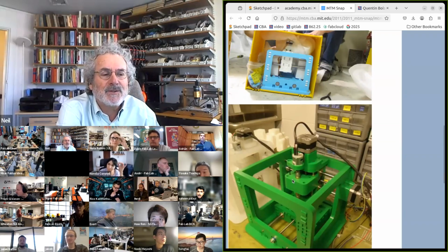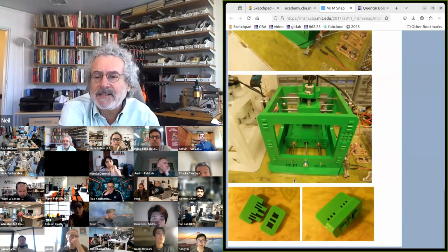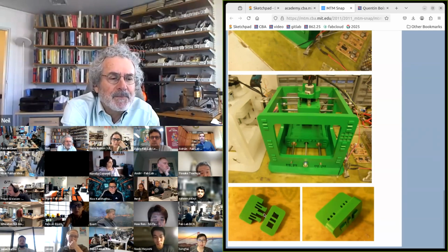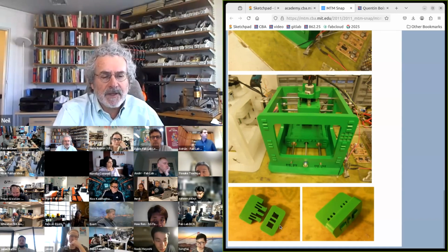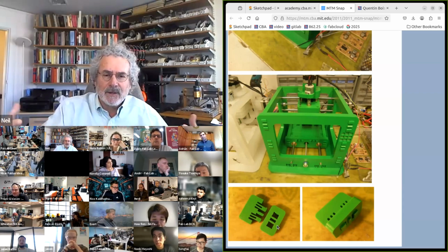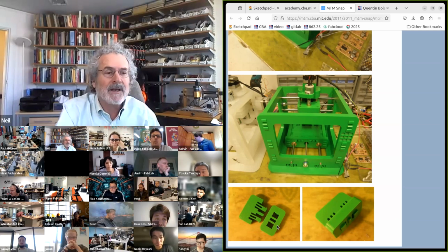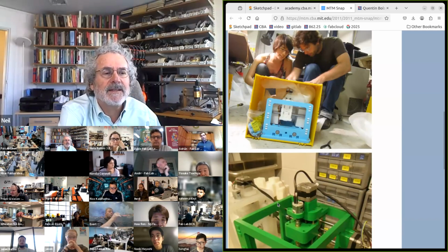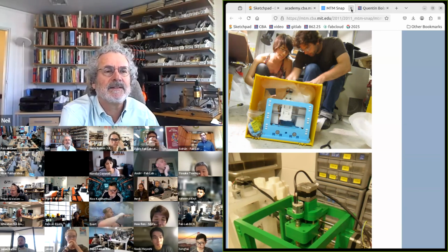This is a self-aligned joint. So rather than bolting together a frame, this was machined in HDPE, high density polyethylene. And if you look at this joint, when you snap it together, the tab centers it. These side beams latch it in. These posts constrain it from rocking. And so just the act of clicking it in takes up all the degrees of freedom. It's reversible, you can take it back out again, but by just snapping it together, you align all the parts of the machine. And so that's a self-aligned framing.